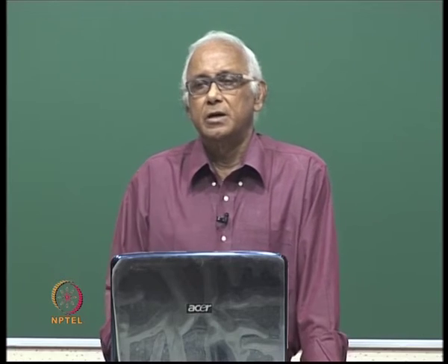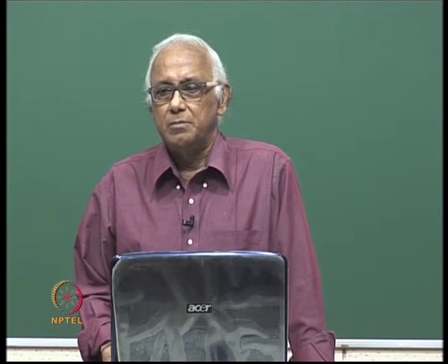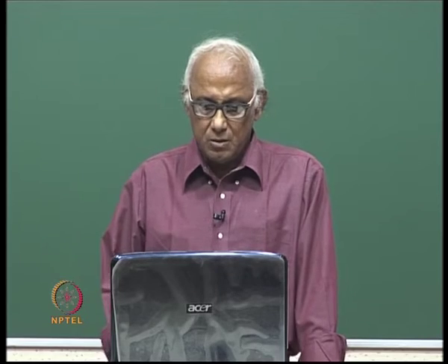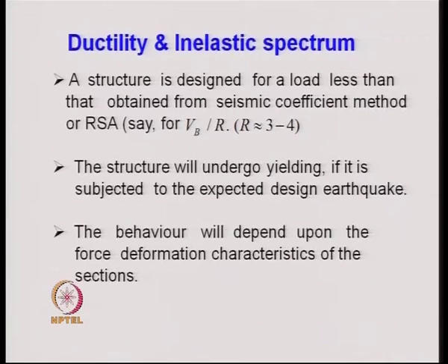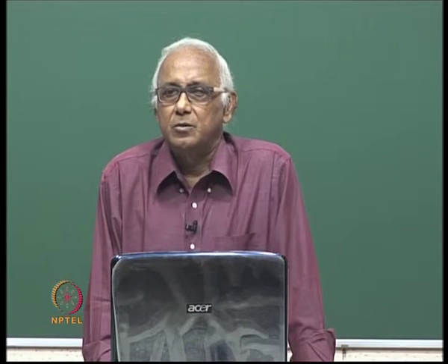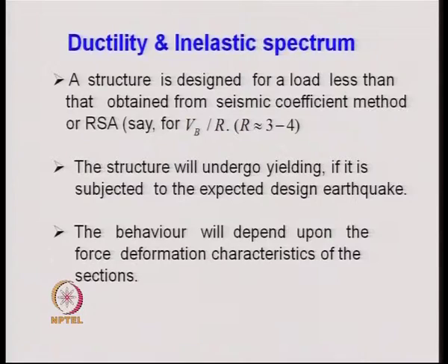For finding out the ductility demand for each element, one has to carry out a nonlinear dynamic analysis or nonlinear seismic analysis of the structure, find out the maximum displacements or deformations that take place in individual members, divide them by the yield deformation or yield displacement, and find out the ductility for each member.